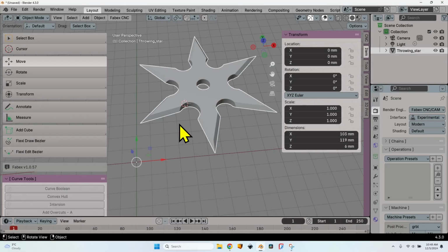This is not something related to FabEX CNC and the way you make the G-code, but I think it's pretty important to first think about what you are doing, how you are going to hold everything down, because this is a big problem and I want to avoid the tabs. So I will make that center hole. I will also make a little bit of recess in the spoilboard of the CNC in order to be able to flip the star again and position it correctly for the second side.